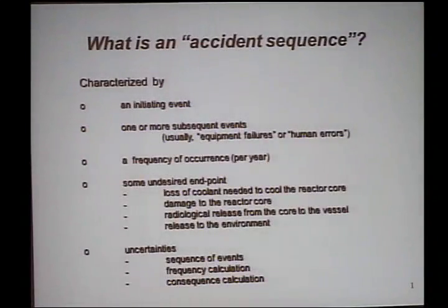And so you work out this sequence in which you have the initiating event, and then the probability that the pump that's supposed to be there to work anyway is only 99%, there's a 1% chance it fails, and then the human makes another error, maybe that's another 1%. And so you work these out, and you end up with an accident sequence that has an initiating event, 2 or 3 or 4 subsequent errors. Some of them are failures of equipment, and some of them are human errors. I mean, there are all these different sequences. There are a few hundred of them. And you end up with a sequence that leads to the undesired core damage accident.